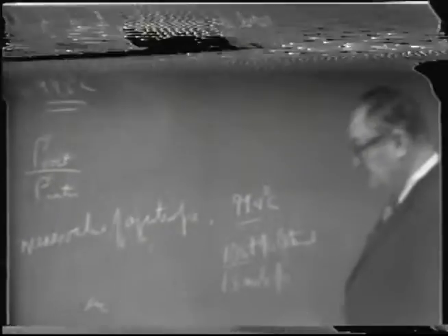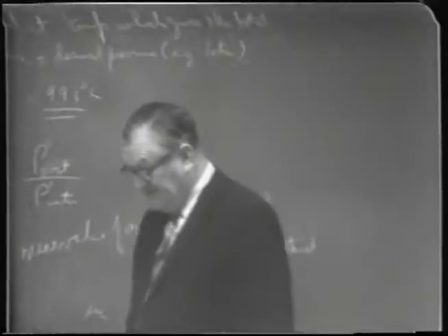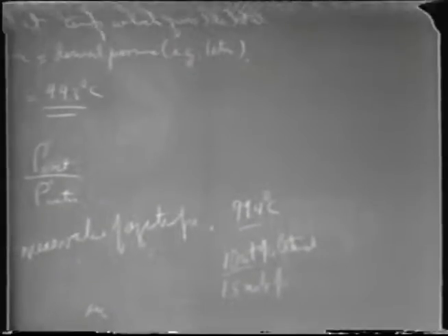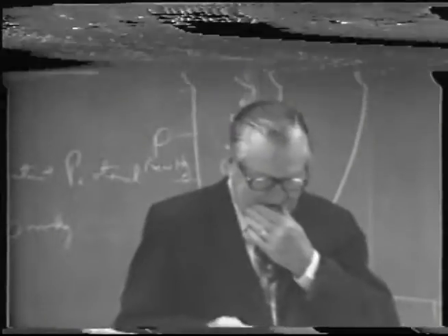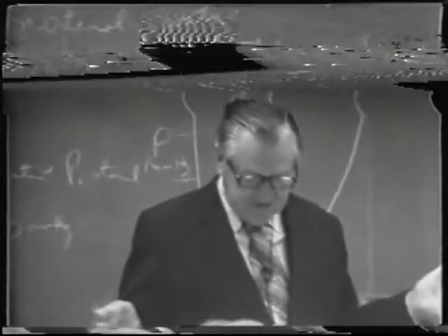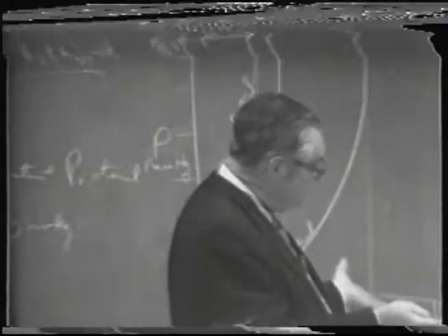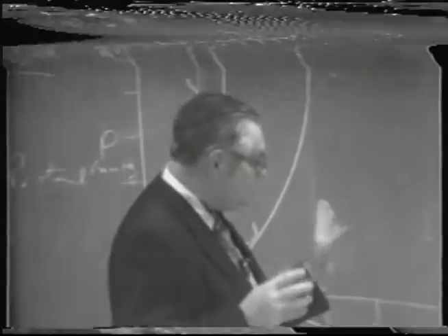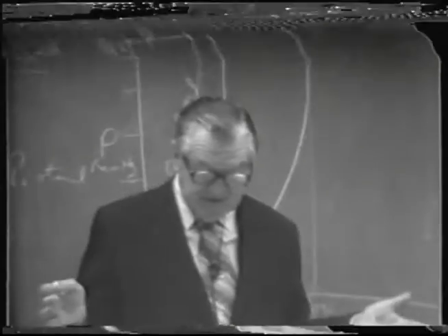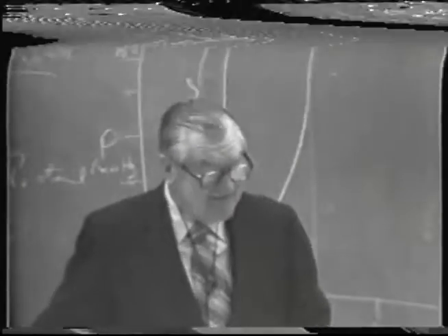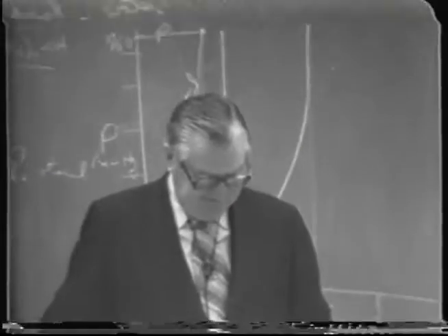Since it has a much higher molecular weight, the percentage on a weight basis is larger. Of course, this would be a heterogeneous azeotrope because the distillate would have both octanol and water, and they would be insoluble in each other, so that'd be two phases of the distillate.